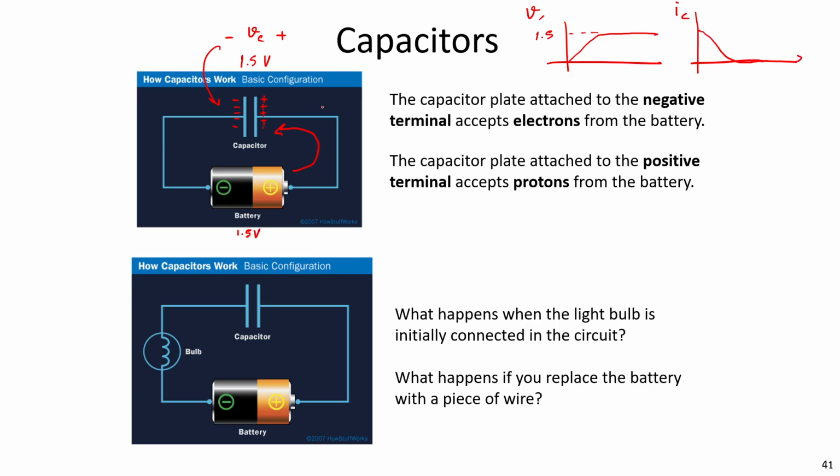Current flows here. So firstly, the current will flow until full charge, and then no current flows anymore because the voltage is staying. So the voltage is like this, and the current decreases until 0. So this circuit becomes an open circuit.